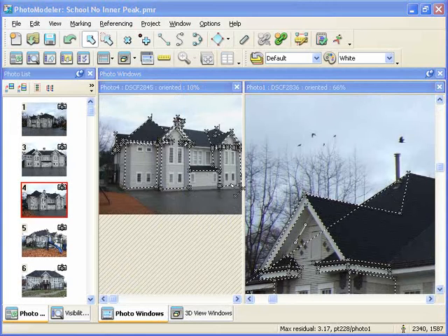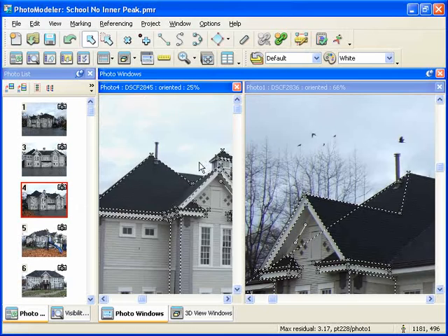The cylinder tool is similar to the edge tool in that it is used to mark along the edges of the cylinder objects, and the endpoints are not important. With the cylinder tool, we mark the 2 visible edges of the cylinder. We will mark this vent pipe here. We pick 2 photos that roll around the cylinder axes, 1 photo from each side.